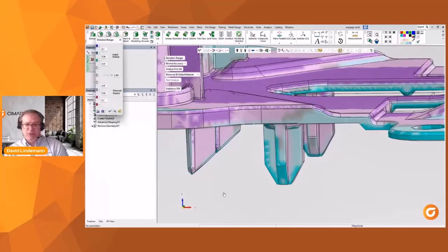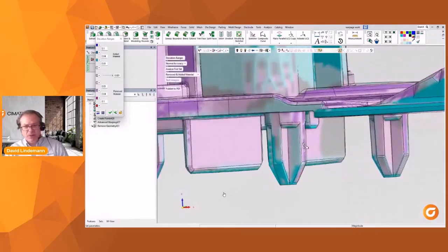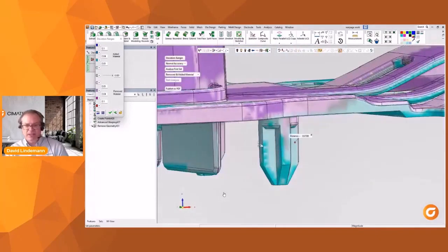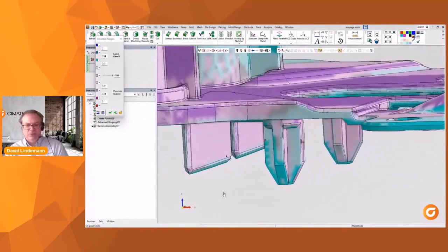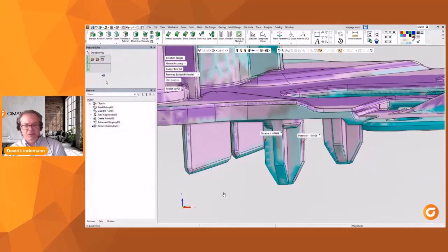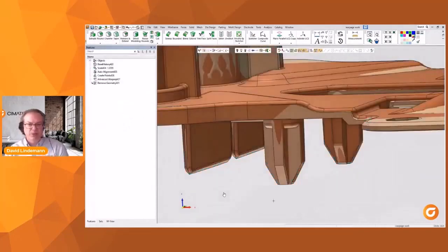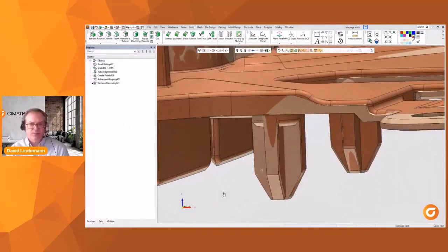Here in this measurement tool, I'm looking at areas where in the blue it's gotten bigger, whereas in the purple it's gotten a little smaller. So I'm seeing the motion, comparing one part to the next, and I can specifically measure exactly how far away one is from the other. All right, so it's a few thousandths. We're going to take that now and push it back to the original, so that it lines up to that position where I know that ejector pin is.